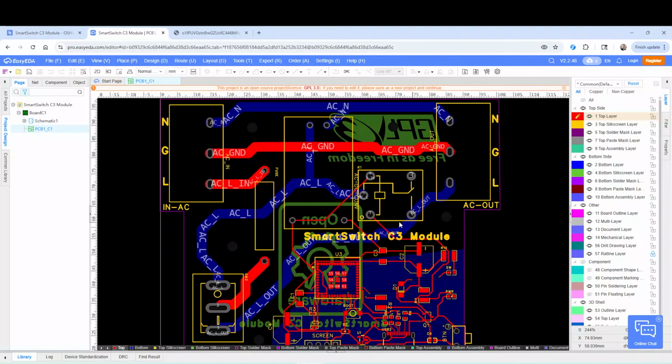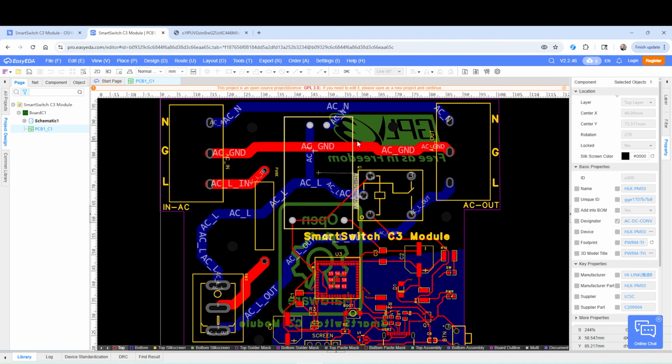Now, depending on the amount of power you need to bring into a design like this and just how much current you're going to be using is really going to determine what types of components you're going to use in your EMI filter. But these filter circuits do generally have a topology that you can follow, and you can then replicate it out to multiple stages if you need to. If you take a look at the PCB, you can see here when this comes in, the design has the AC power going directly over to this AC to DC converter module.